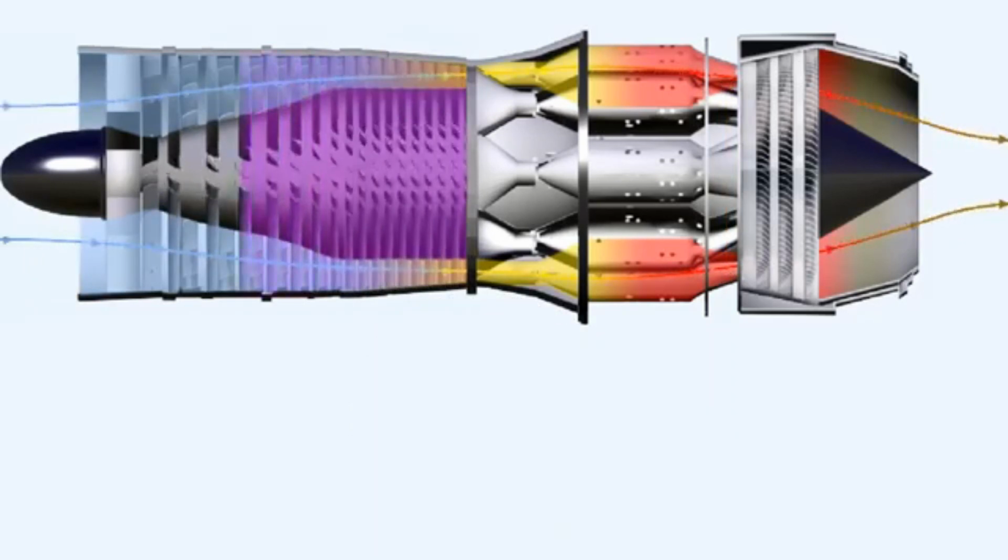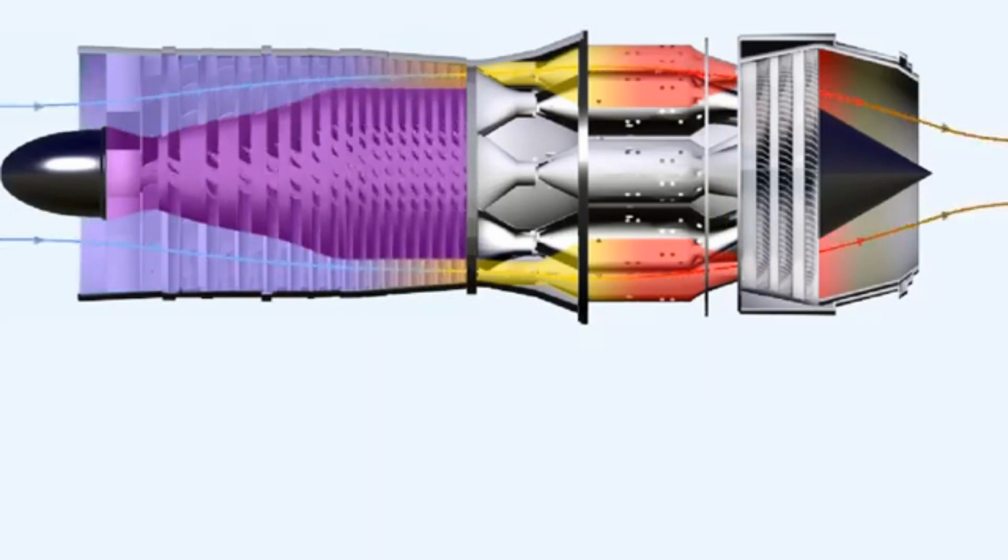Remember that compressor stall is a progressive phenomenon. It could, in theory, initially occur at just one blade, subsequently worsening to encompass the whole of one stage, and then, if nothing is done to prevent it, it can affect the whole engine. The progressive deterioration of the speed of the airflow through the engine, caused by the stall phenomenon, will eventually cause a complete breakdown of airflow through the engine, which we said was called a surge.